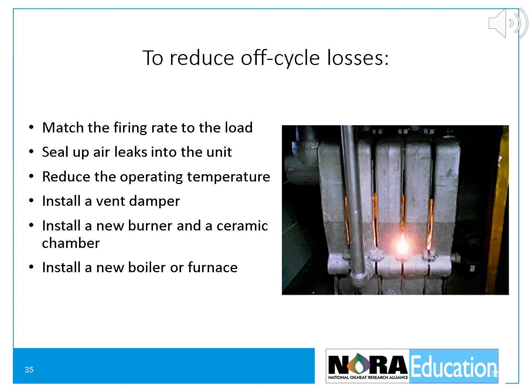Never underfire a steam boiler. Never underfire a boiler with a tankless coil because the customer will run out of hot water. Or any unit where the net stack temperature drops below 350 degrees Fahrenheit.